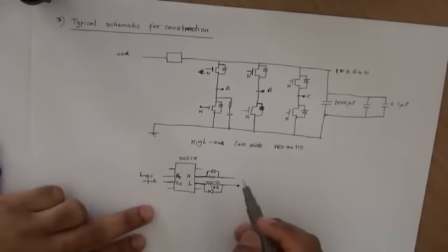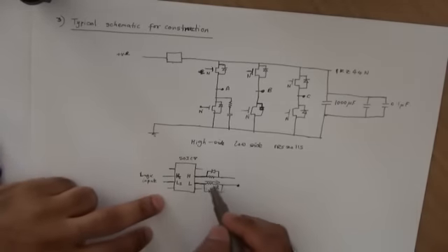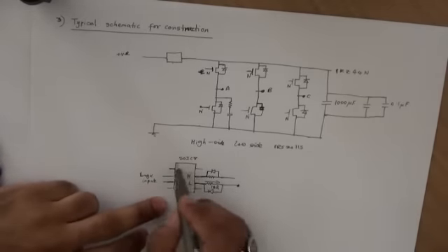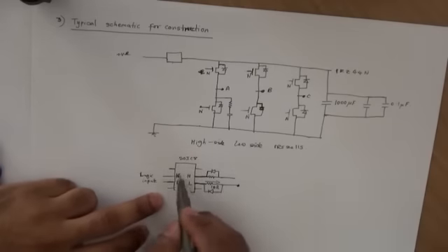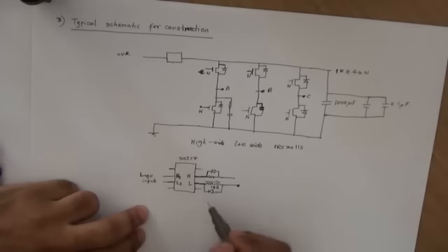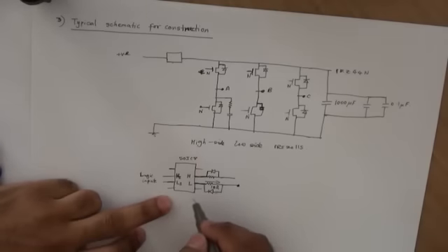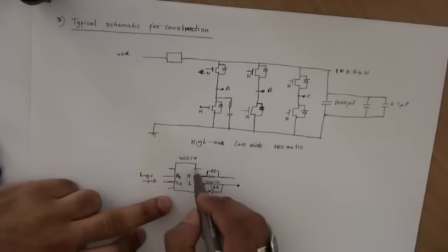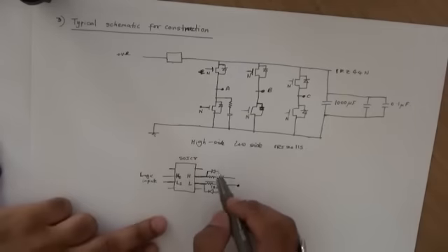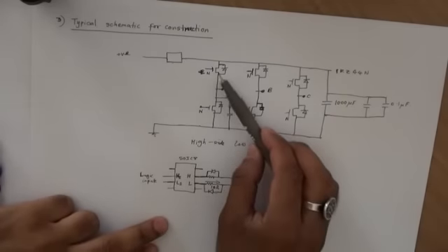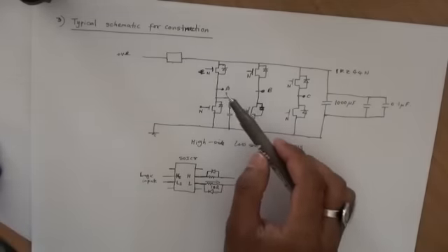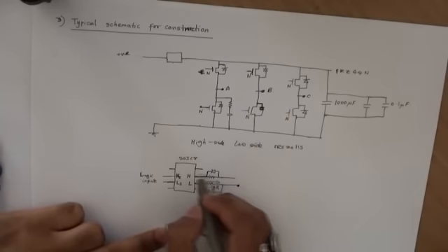With the filter capacitors, you would also want to have filter capacitors across the supply to these high side, low side drivers. The other thing is the purpose of having these high side, low side drivers is to really turn the high side MOSFET on, and to do that they use a charge pump capacitor.